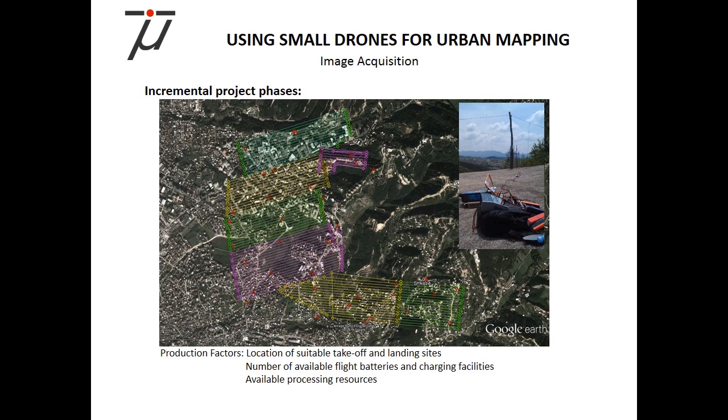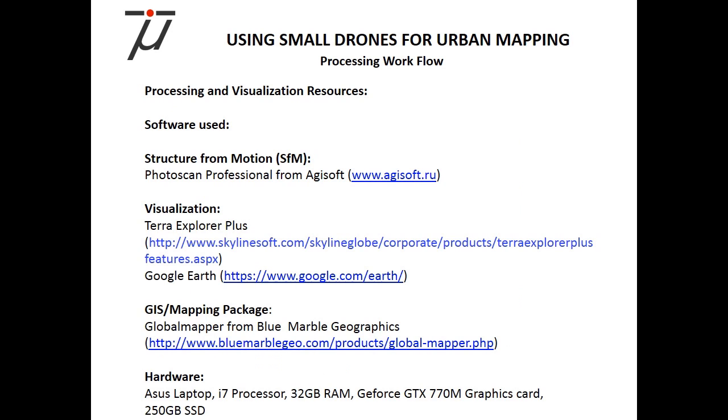So we ran around with the GPS navigator, climbing up and down buildings to find the building elevations from which we were going to take off, because all of the flying heights are relative to takeoff position, so you need to know what you're doing elevation-wise. And so we designed this whole lot to be more or less 50 meters above rooftops. That would give us at rooftop a resolution of about 13 millimeters, and at the bottom of these buildings, anything up to 25 millimeters. All right, and also at the bottom of the valleys.